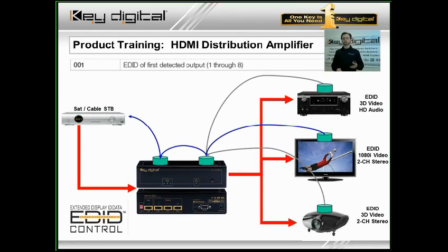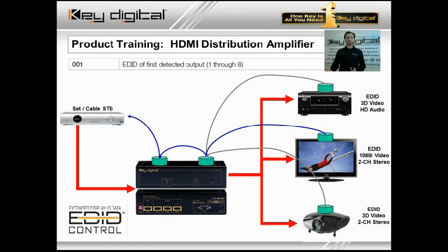Now let's say, for example, we follow the blue line and the flat panel display is the device that powers up first. And typically that's going to be the case if you were to power these all up at the same time. Projectors are typically rather slow to show you picture and slow in their boot up process, as you know, and typically the EDID is not immediately given to the source. An AV receiver perhaps can also be a little slower than, say, just a flat panel display on the wall, where that's usually the quickest device out of this sort of scenario to provide its handshake.